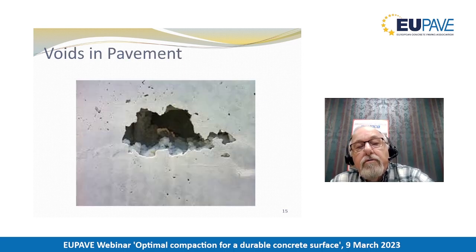Well, there are also non-surface issues that come from poor vibration. Lack of consolidation causes voids in the pavement structure. I'm a pavement designer besides being a materials guy. So as I look at this, what it speaks to me is that that area of the pavement is going to be less structurally able to carry the loads that are imposed on it. I'm going to get premature deterioration. If that's widespread, it's a mixture problem that maybe or maybe not can be compensated for with vibration.